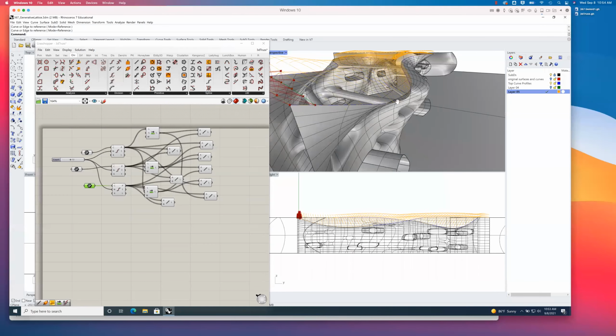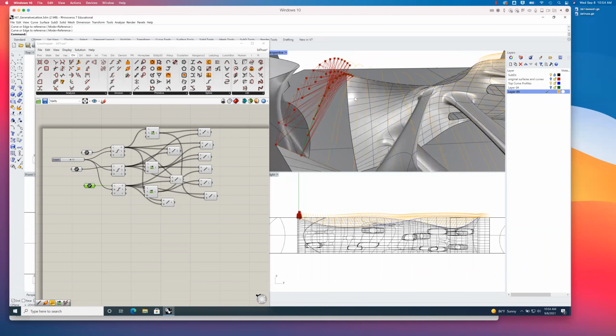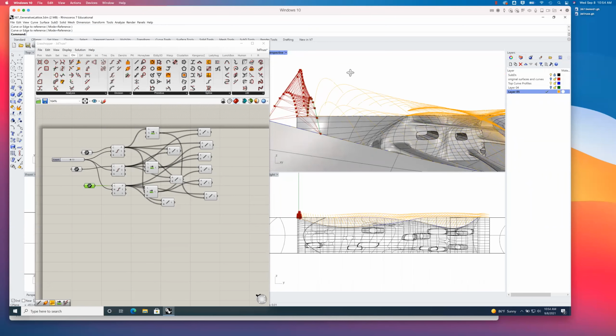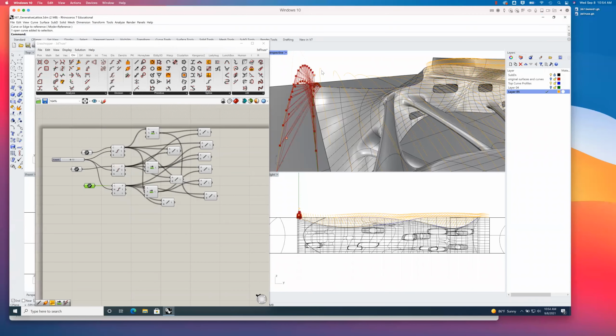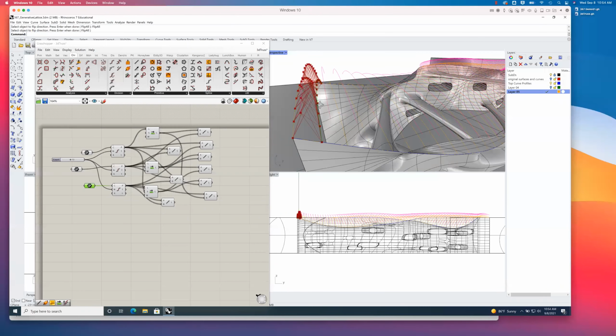All right. Now I have some sort of directionality problem. I suspect it's this way from both ends. So it's these top ones, for some reason. So I'll go ahead and SEL last, select the last items that were generated, in this case, a copy. Okay, SEL last. And I'm just going to go to Analyze, Direction, Flip All. All right. Hopefully that fixes it.